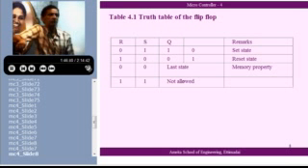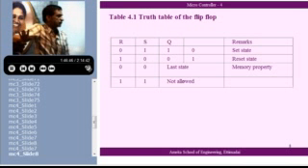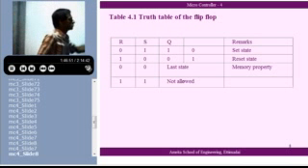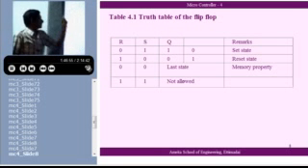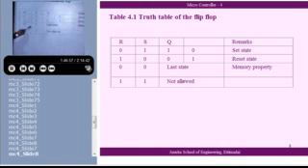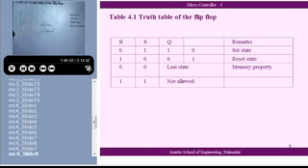There is a 1 earlier, that is retained as 1. There is a 0 earlier, that is retained as a 0. The last state is retained here. So when you go back from 0, 1 to 0, 0, that state is retained. From 1, 0 to 0, 0, this state is retained.